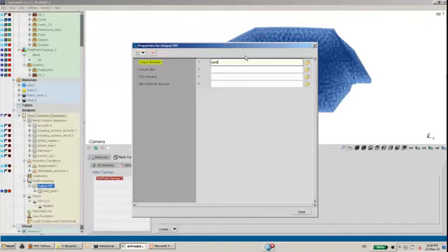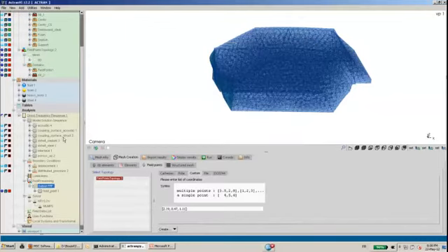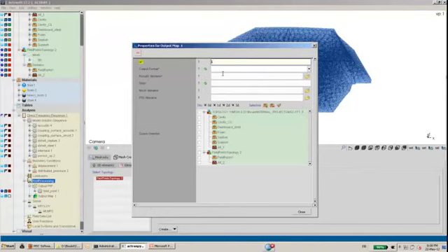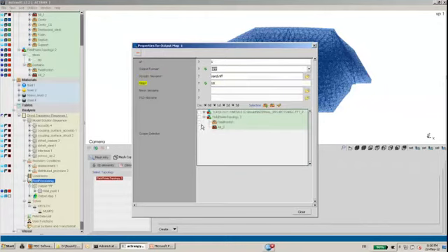results will be stored, and it's called a PLT file in Actran, and so this will be named sand.plt, sand for sandwich. Then I may also want to have maps of the analysis. So for that I need to create an output map component. I will take the format as the NFF format, which is the Actran format. The result file will be called sum.nff, and I want that to be output every 10 frequencies of computation. And I want the results to be stored on the cavity, sorry, on the dashboard for having the deformation.